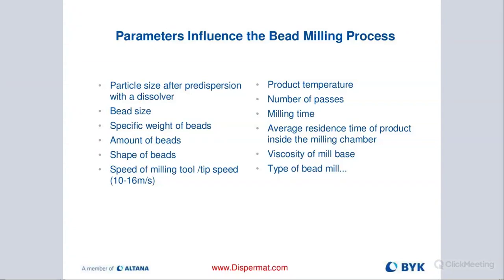If your mill is using all that power available, then you would definitely want to match that, and maybe even go a little beyond that with your chilling system to optimize the cooling process and ensure that there is no heat buildup that the chiller couldn't handle. So always look at the kilowatt output of the Dispermat and match it up to the chiller. Never buy chillers that have less output than the actual dissolver.